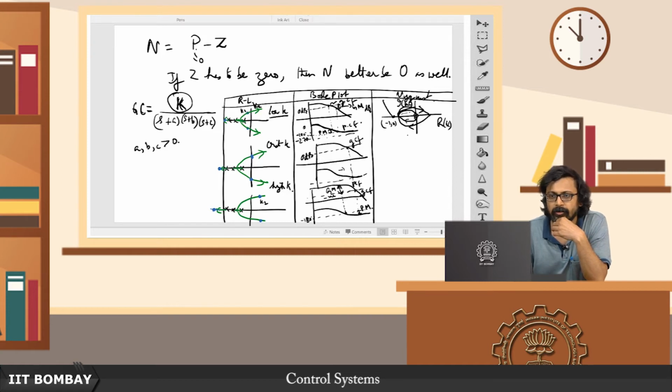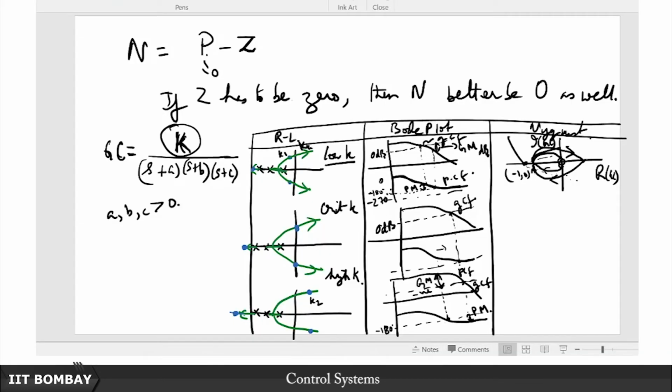So it really matters not. If you drew this test radius through this point over here, once you will see it cuts in this direction and once it cuts in the opposite direction, one counterclockwise and one clockwise. So the net encirclement is 0. You can try out several scenarios and you will find that no matter what test radius or test phasor you choose, it is always going to give you 0 encirclements. That is consistent with what we understand.